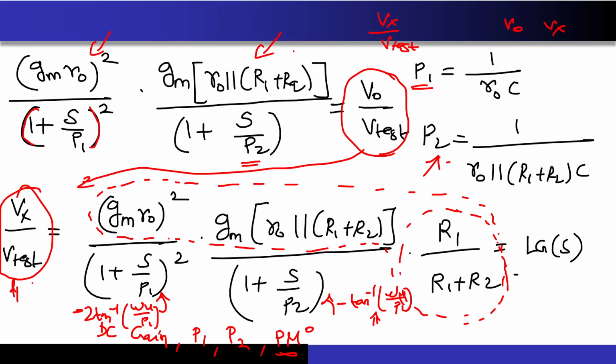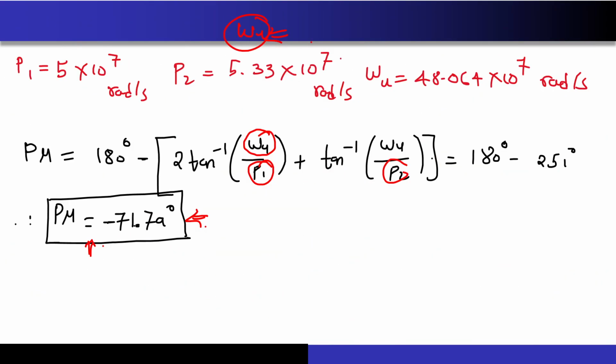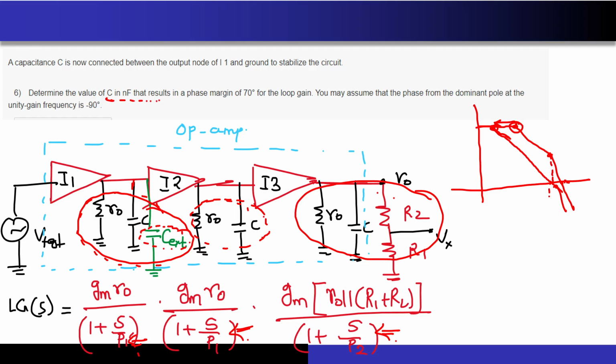Okay, sir. But since we have the third pole different, like we can't do that here, I guess. Since we have the third pole including R1 and R2, we can't do the A-beta analysis here for the loop gain expression. Just give me a second. Can you repeat? I didn't get your question. No, sir. I'm saying that since we have the third pole different here, with R2 and R1 included, we can't multiply A and beta here.